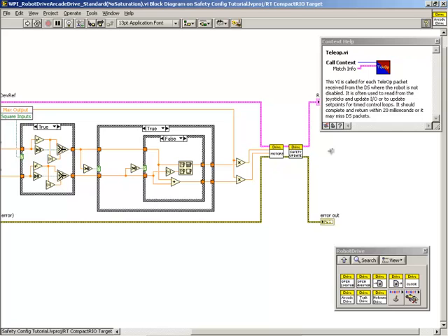This VI must run faster than the timeout value that was set in the safety config VI within the robot drive VI back in begin. If the loop is not running fast enough, the motors being controlled will be stopped until the safety output is updated again.